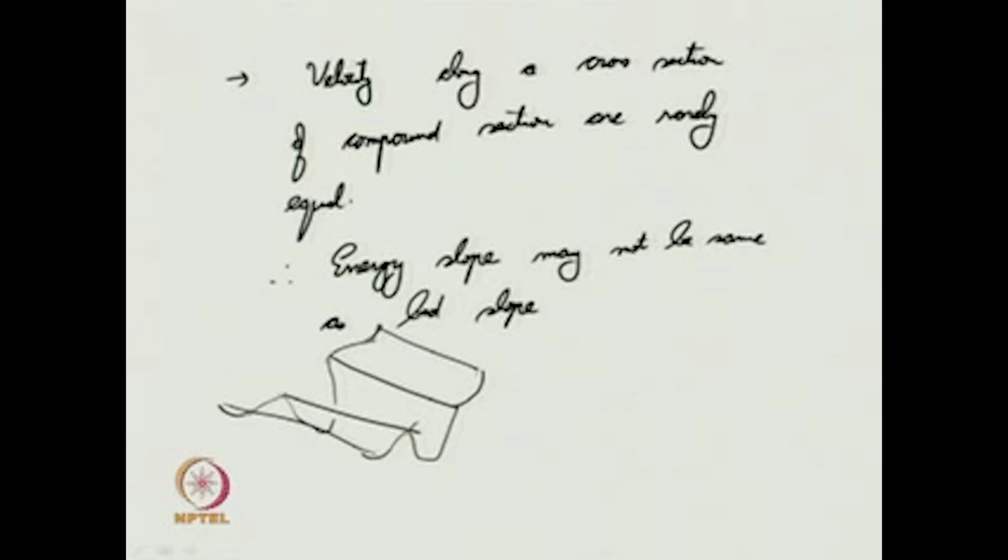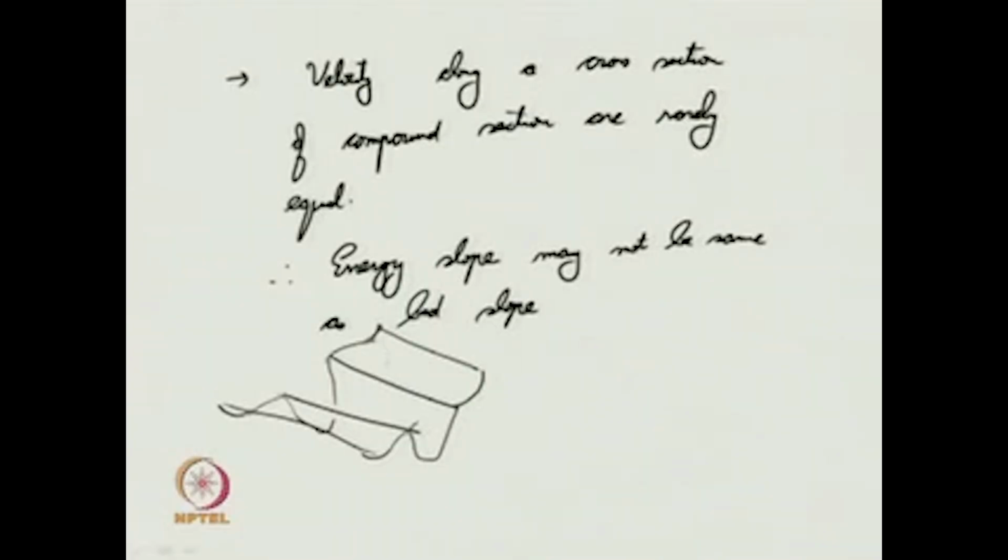So, in such a type of channel portion, along the flood plains or along the side channel portions and all, you may have to incorporate different velocity. In the main body it will be a different velocity. Subsequently, along this entire reach, how much discharge is available from the flood plain, as well as along the main body, the combined discharge and all, how to evaluate them.